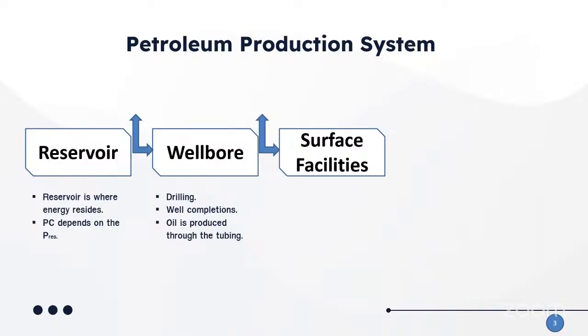The next thing is the surface facilities for onshore. The surface facility begins with the wellhead, which houses our tubing head housing, casing head housing, and the like. Then the next thing that follows is the Christmas tree, which contains several valves for regulating our production from the wellbore.